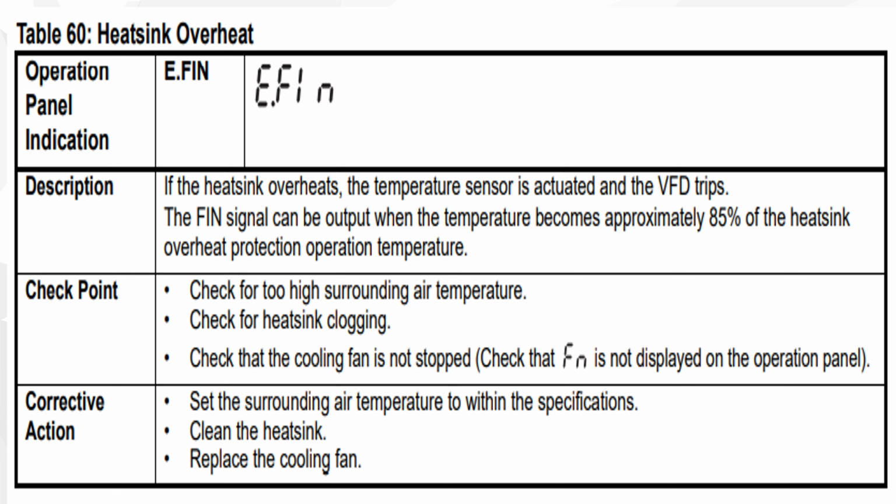E.fin, heatsink overheated. In the VFD there is one heatsink. Heating is generated by VFD internal cards like power cards and control cards. For that we use one heatsink that will reduce that heat energy, so the inside temperature will be maintained.